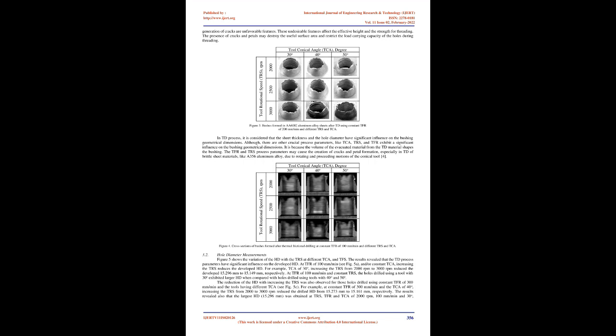After drilling, the workpieces were cut, from the center of the hole, using a wire cut machine, and the HD, BT and BH were measured. The BT was measured at the middle of the bushing height, BH/2.